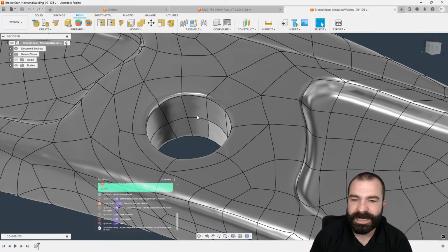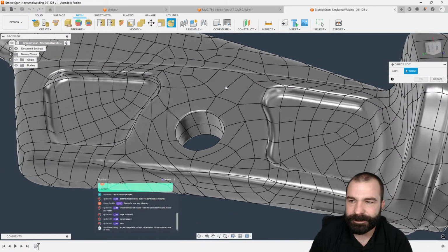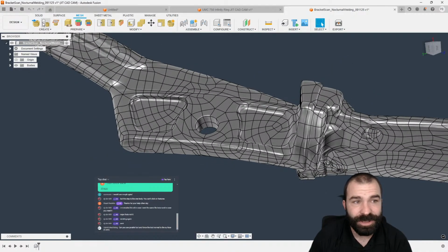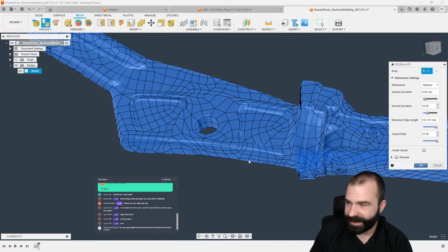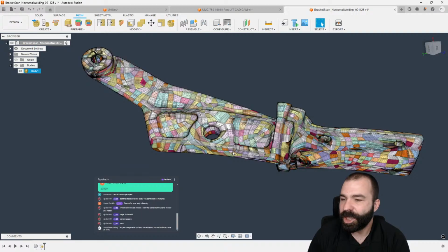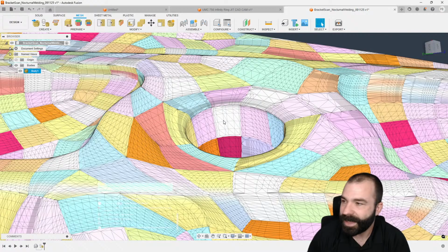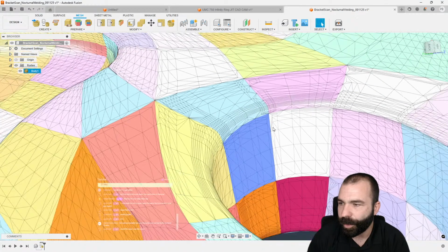As you're seeing here, I could manually create those as well. We're going to go ahead and do direct edit. Actually, this is a solid body, so this is where we have such a great time. You're going to have to tessellate this based on that body. What this is going to do is refine everything. We'll give it a second here. This is one of the things inside of Fusion where we really have to focus on computing power. Your CPU really does make a big difference. But as you can see, I don't know if you guys can see this, let me know in chat, we actually have a fillet at the top here versus the hole or the bore itself.